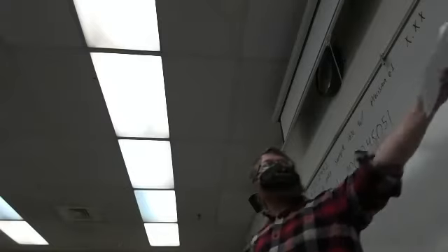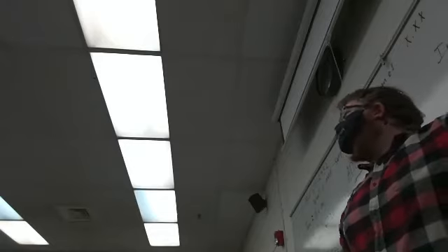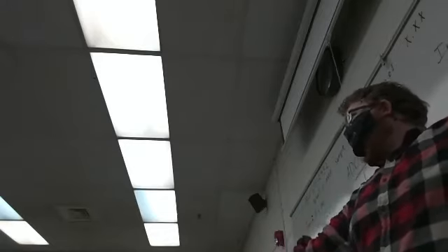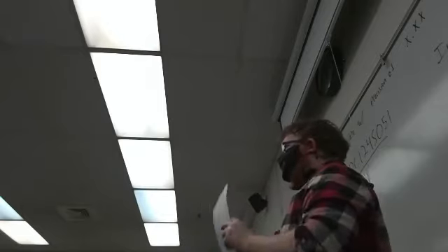Well, now the D to A doesn't have that ridiculously long conversion time. But what does count as overhead is all of those acknowledge bits and the address bits. And in that case, depending how long the packet is, you might even have to factor in the start and stop conditions, because those are not transmitting data either. You get most of the points if you ignore those, but that is part of the overhead.